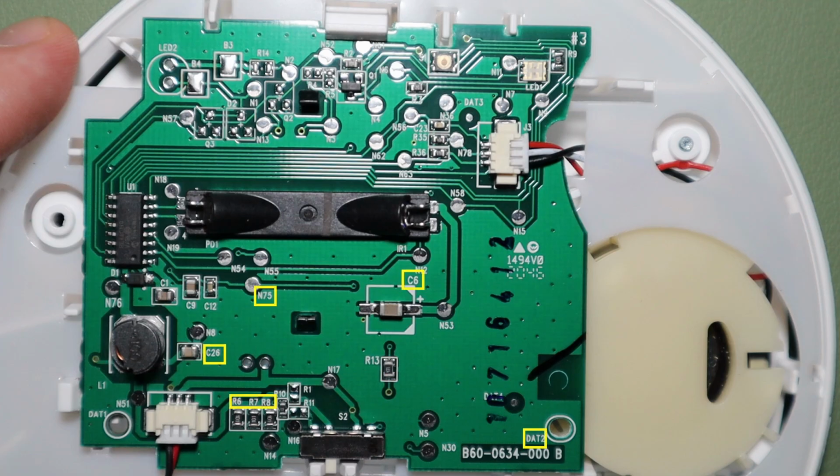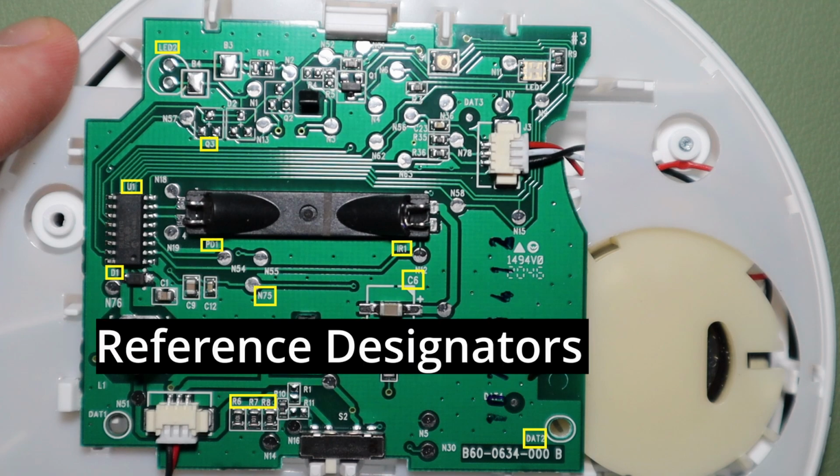markings on the PCB. While not all PCBs will have the same markings, the First Alert board makes it easy to identify the different components used within their circuits. The tiny white letters located throughout the board are called reference designators, or as some call them, component tags. These do exactly as the name implies. They designate or tag the various components on the PCB.